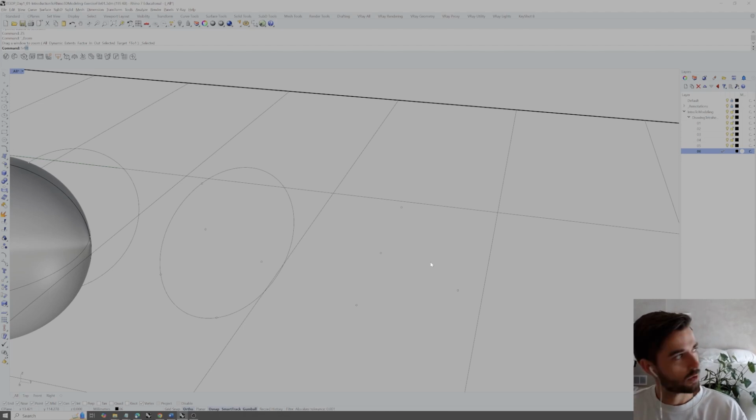So if I type surface point and then hit enter, this is SRF-PT, which is abbreviations for both of those, and then hit enter, we see an option for adding the first corner of the surface. So we can do our base first. So I'm going to just choose, let's say 1, and then 2, and then 3, so third corner of the surface. And then we also have an option for the 4th corner of the surface. So if I just hit enter, we would finish this with 3 vertexes.